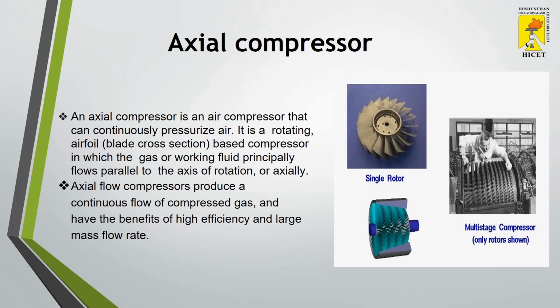A single rotor and a single stator combined together form a stage, where the rotor is a rotating blade and the stator is a stationary blade. The rotor imparts the kinetic energy on the blade and the stator converts the kinetic energy to the pressure energy. When the rotor is rotating, the kinetic energy as well as the pressure energy increases. Altogether, in a stage, the pressure will increase.